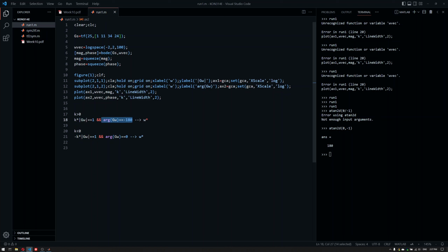Since this is not depending on k, this is what we search for at the beginning, because the system does not change, the Bode plot does not change, so this condition doesn't change. If there's no such frequency, then there's no stability boundary. If there's such a frequency, then this is a candidate point that we should look up. And if the multiplication here can also be satisfied at that frequency for that value of k, we will have a stability bound. So let's look this point up and try to come up with the stability point.